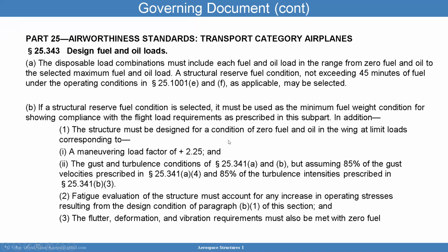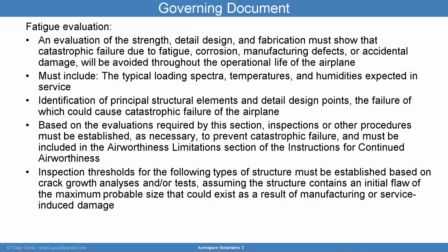The structure must be designed for a condition of zero fuel and oil in the wing at limit loads corresponding to a maneuver load factor of 2.25 and gust conditions in these sections. But assuming 85% of the gust velocity is prescribed here and 85% of the turbulent intensity is prescribed here. Fatigue evaluation of the structure must account for any increase in operating stresses resulting from the design operations, and flutter deformation and vibration requirements must also be met with zero fuel. Again, you have to meet the zero fuel conditions as shown here.